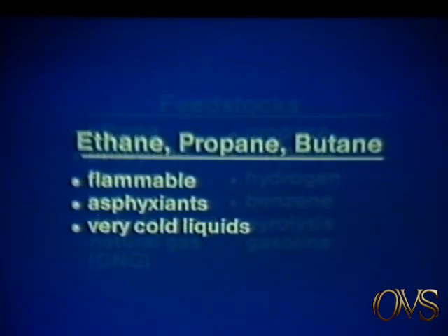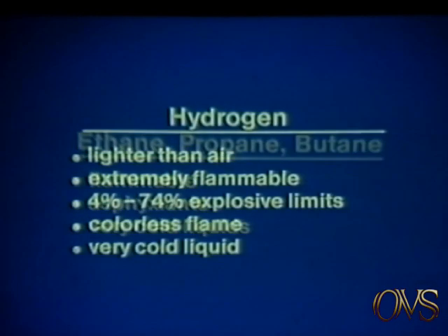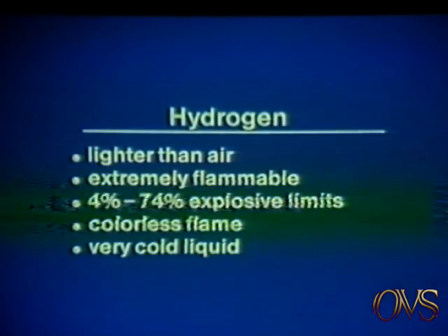We've already mentioned ethane, propane, and butane in the section on NGLs. These gases are primarily simple asphyxiants, which may cause dizziness or drowsiness in higher concentrations. Their major hazards are extreme flammability and freezing effects, since they are pumped and stored at temperatures and pressures that keep them liquid. Hydrogen is not technically a hydrocarbon, since it is pure H2 gas without carbon atoms. Hydrogen is the lightest gas. It will quickly dissipate into the atmosphere, but it may accumulate at ceiling levels.